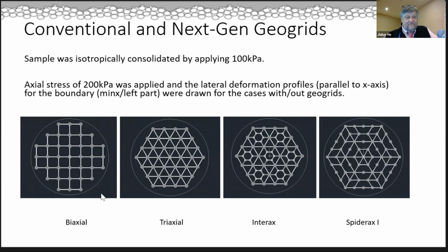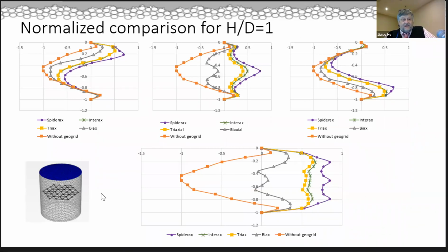And so what we've been doing is we've been looking at where we place those geogrids at different elevations within the triaxial samples and apply loading. We're looking at what happens to the form shape. In the plot here, in fact, the upper one on the left is the grids. The grid is placed at the 1/3 point. It's placed at the midpoint in the middle of the plot on the top, and it's placed at the 1/3 from the bottom in the plot on the right. More importantly, in the larger plot at the bottom, we actually put 3 grids in there. And so you can start to quickly see where the presence of the grids actually constrain deformation.